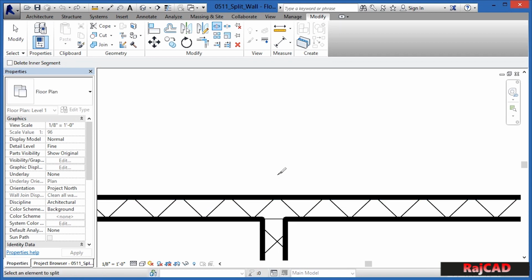Now, on some monitors, you might see a line going straight up and down at this point. It just sort of depends on the computer that you're at. Hit Escape a couple times on the keyboard, and one of the things you'll see is if you highlight over the left-hand side and then highlight over the right-hand side, that this wall is now split in half exactly in that location that we just selected at.